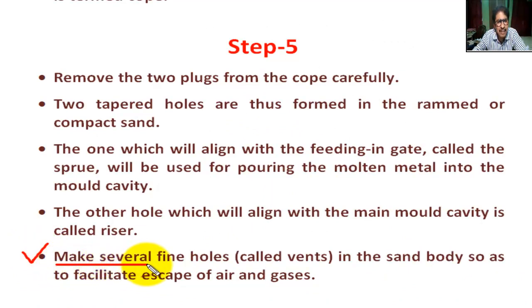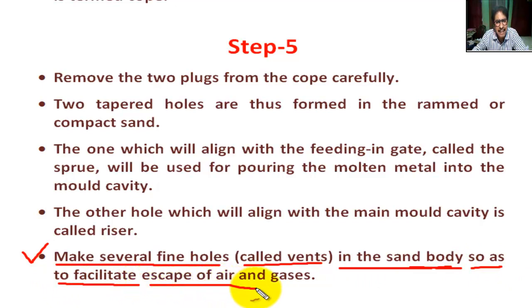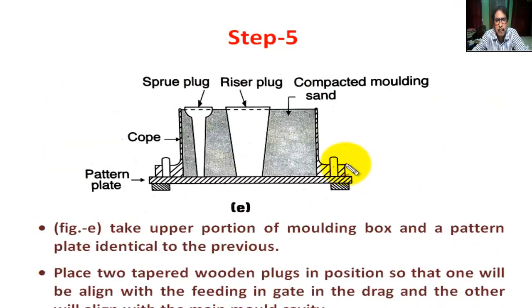Also make several fine holes called vents in the molding sand, so as to facilitate escape of air and gases.